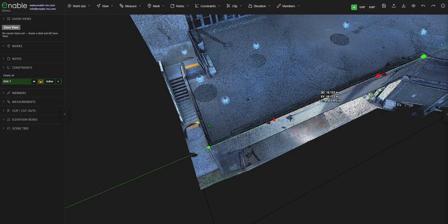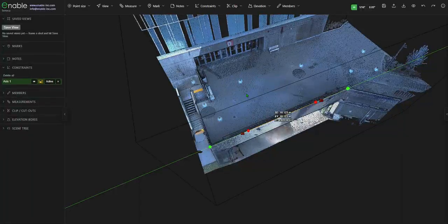If you want to apply not an axis, but a plane, say for the top of the slab here, you can also do that. First thing we'll do is we'll deactivate this. So we left click the active button, and now we can take our measurements from anywhere again. But what we're going to do for this demonstration is we're going to apply a fit plane now. And here we left click, and you'll notice it asks us to set 3 points because we need 3 points to set a plane. You can set more if you wish, but you cannot set less because 2 is an axis.